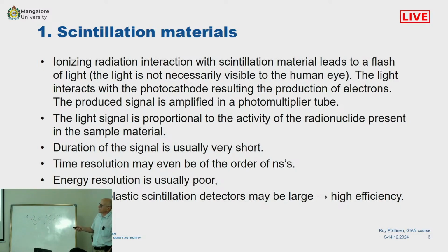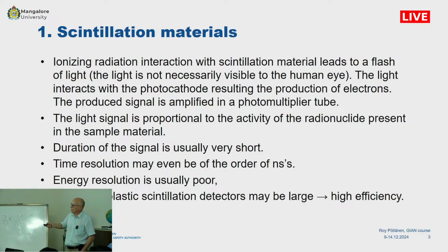This is sometimes very useful. I mean, the duration of the signal is usually very short. This is sometimes quite good in coincidence spectrometry. And because the signal is very short, the time resolution is also very good, much better than what MCA, multi-channel analysis, usually, or hybrid germanium usually has.